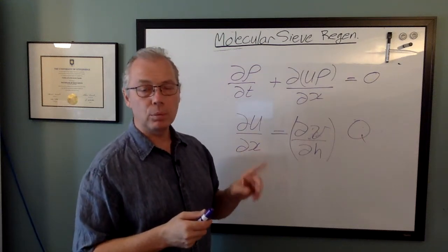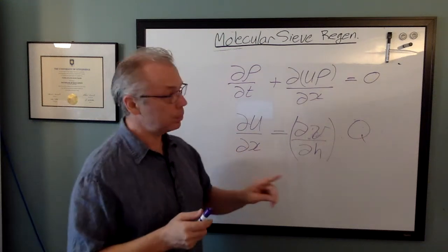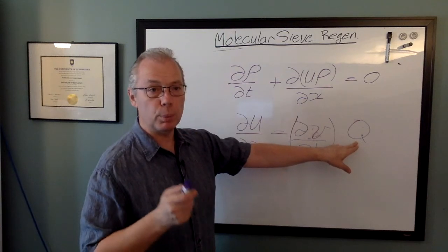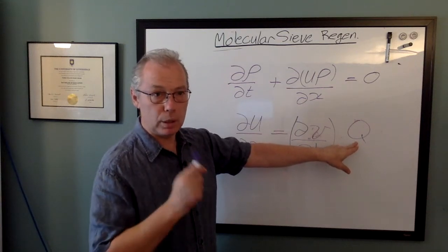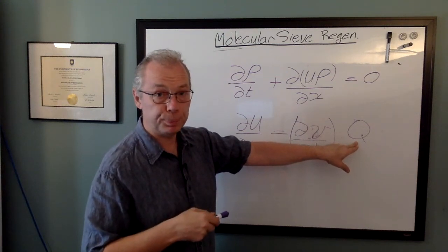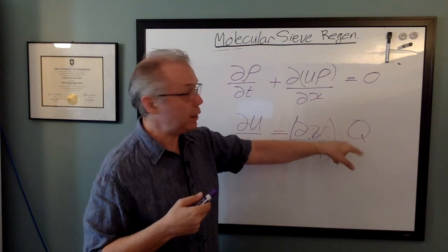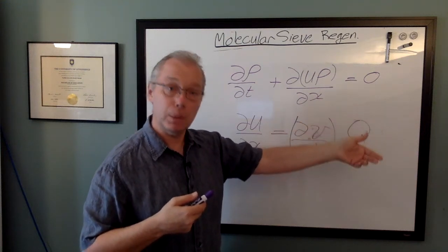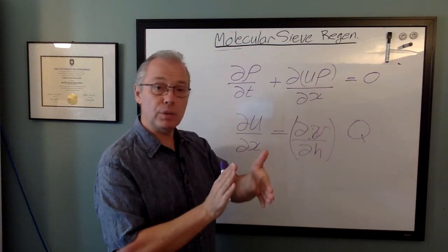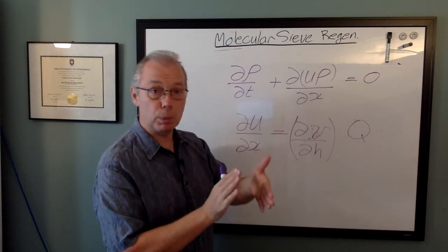We're not quite done. We have one more equation that we need. We need an expression for the amount of heat that is absorbed by the fluid on the inside of the tube. And this must be related to the heat that is provided on the outside of the tube. And what's in between is some thickness of steel wall, which has some thermal mass.